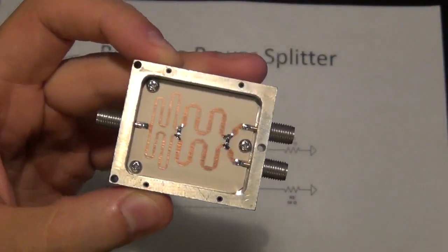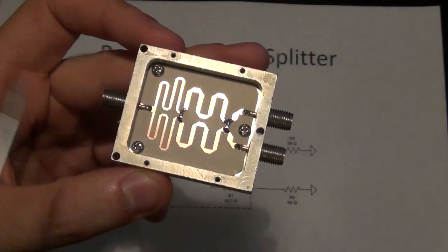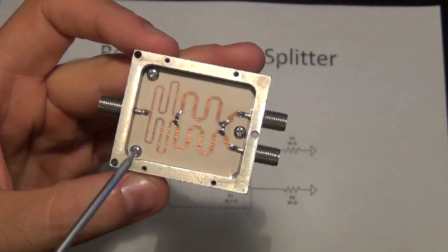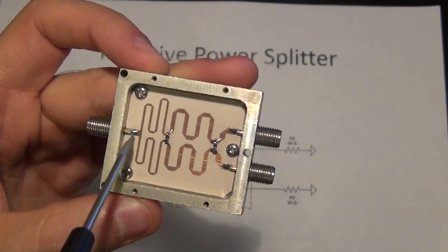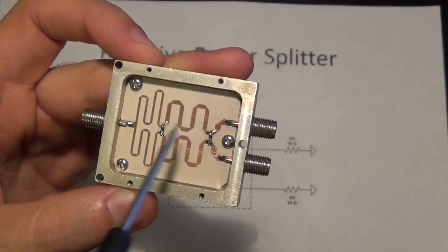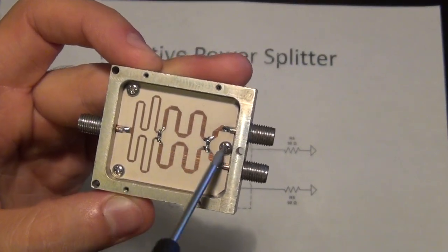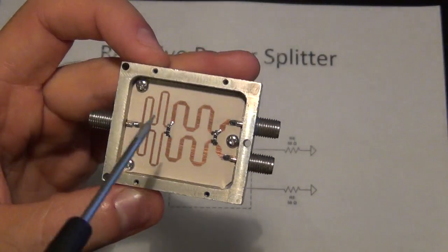Now I'm going to have a totally separate tutorial where I go over microwave design, what all these lines mean, how they work, how we design them. But for now, the only thing we need to worry about is that if you look at this signal, it's connected to this trace at the top and it's connected to this trace at the bottom, and these two traces have 2 small resistors in between them. This is actually a multi-segmented Wilkinson divider, but we'll get into that later.